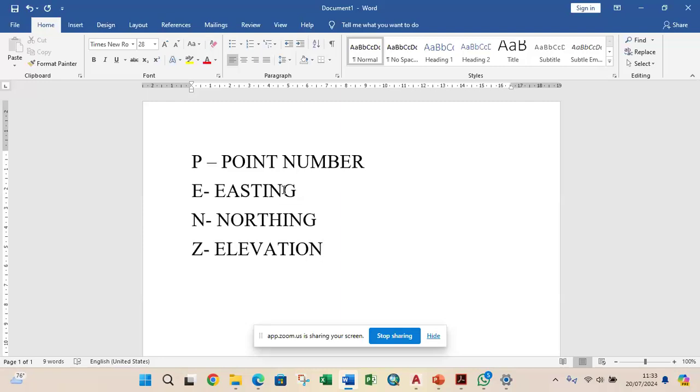If he's working somewhere in the southwestern part of Nigeria now, Lagos, Ondo, and all that, those are all in zone 31. Then the other region, zone 33, is in Adamawa and Maiduguri. So he's going to do a proper projection and setting out of that particular area where he wants to capture his data, before he proceeds in capturing it.